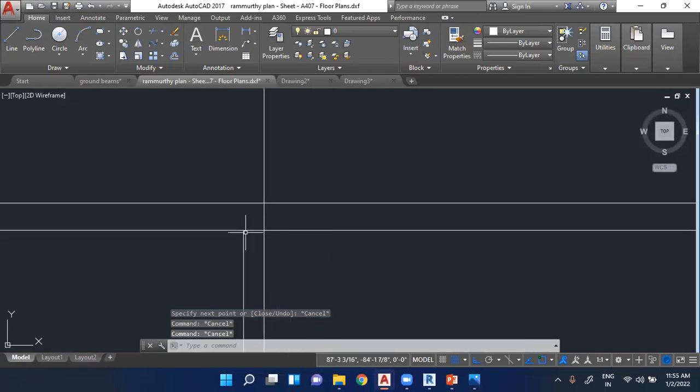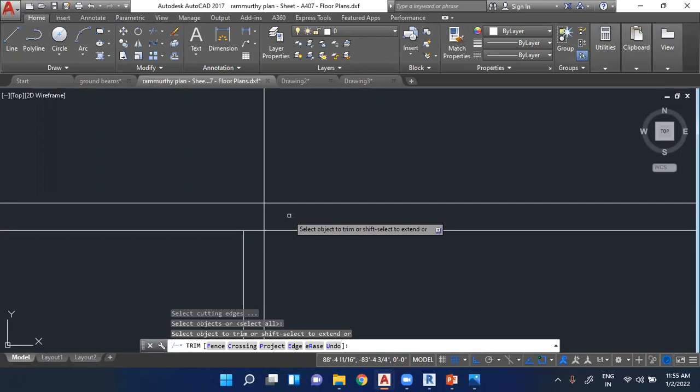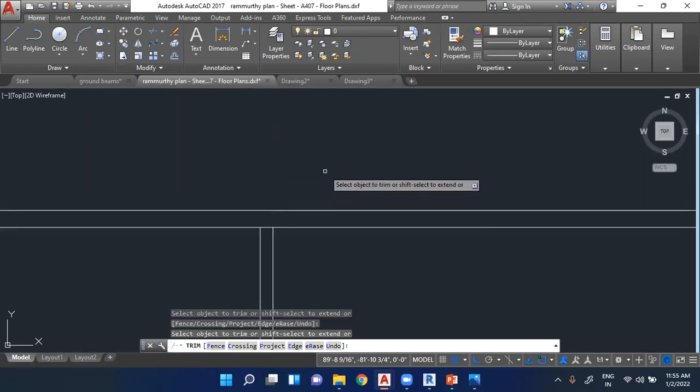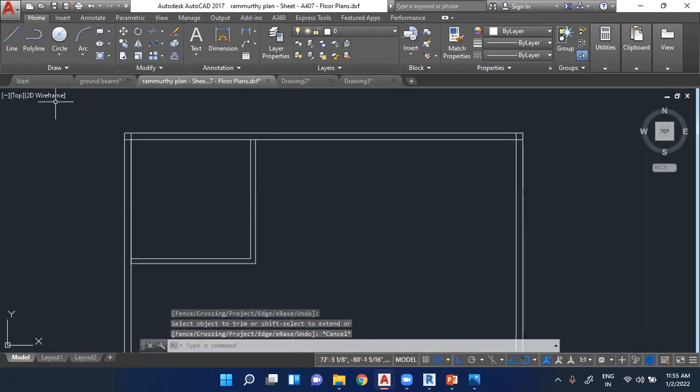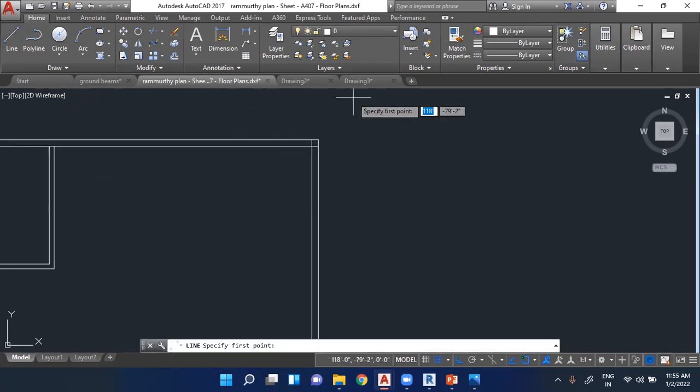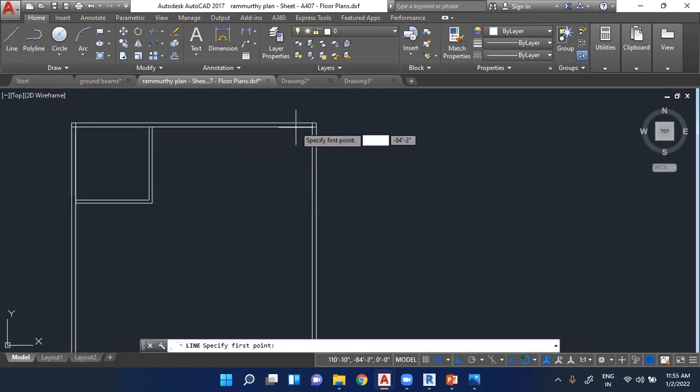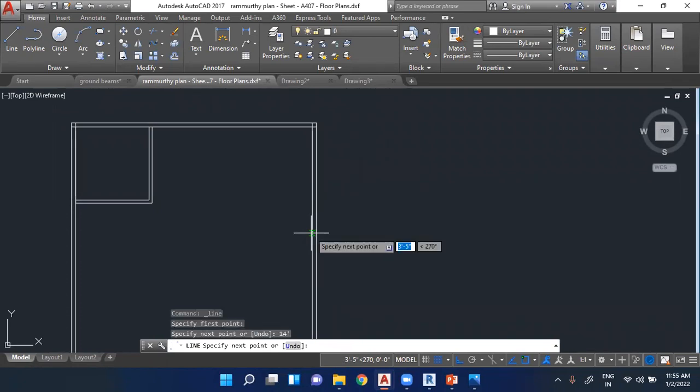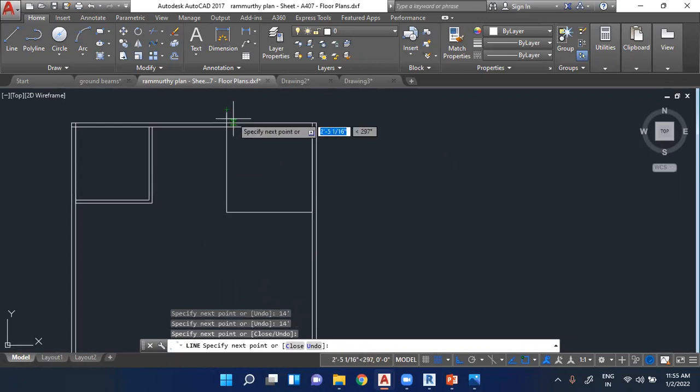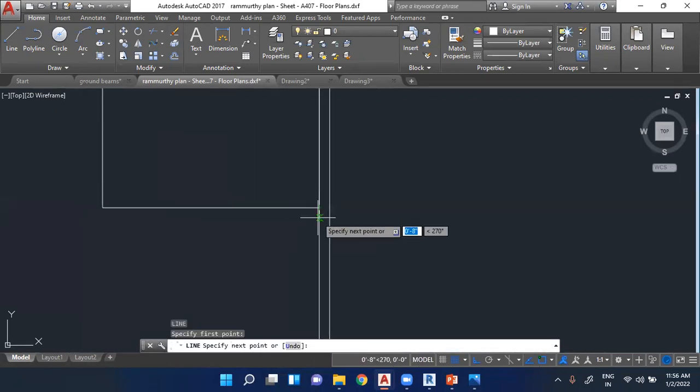Yeah, the line extended above the outer lines. Then I'll use the trim option here. I'll left click the mouse button on the interface, and I'll just hover over the extended part, and it'll delete it. And another bedroom, that's the master bedroom, I'll plot it 14 feet by 14 feet. Thickness 6 inch.